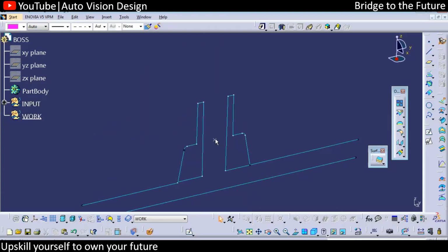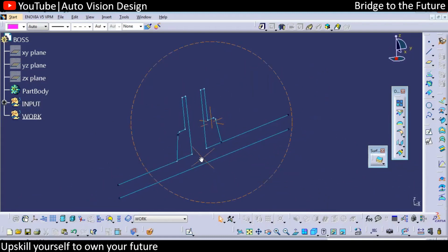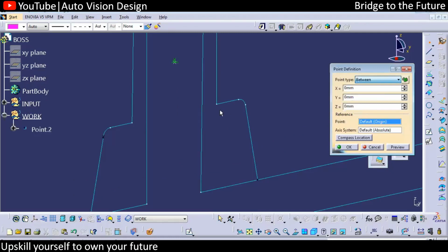So if we have the point, that is good, but if we don't have the point, I can find out the point for this particular section. So first of all, we need to identify which section this is. Okay, so this section looks like a boss with respect to a rib, and that we can identify. It will be the heat stacking boss. Okay, so for that we need to find the point. So we can create the point with between, something like this.